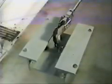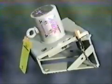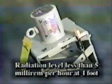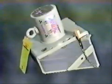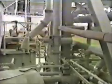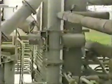The source capsule is placed in a lead shield, which is surrounded by a steel housing. Enough lead is used to reduce the radiation level 1 foot from the housing to less than 5 millirem per hour. In some cases, screened enclosures are installed to prevent personnel access to the radiation beam. In addition to these engineering controls, administrative controls are instituted at local plant sites, depending on what types and quantities of radioactive materials are being handled.